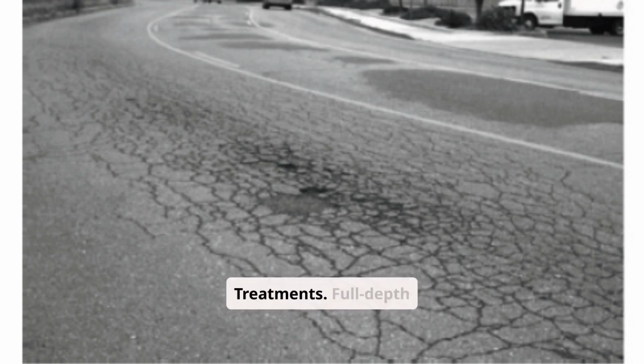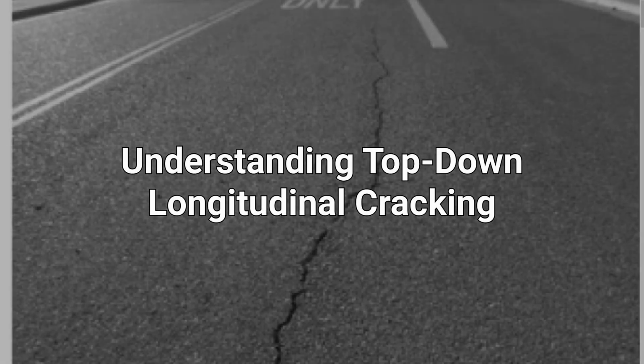Treatments. Full-depth rehabilitation is the best option to get rid of large cracked areas. As alligator cracking starts at the bottom of the asphalt layer and propagates upward, replacing a part of the asphalt layer or overlay does not eliminate this cracking. However, replacing a part of the asphalt layer or overlay can be used for low-severity alligator cracking to defer the high-severity cracking for a few years.